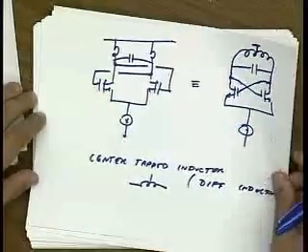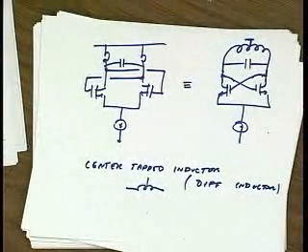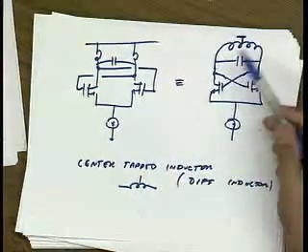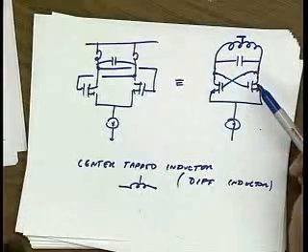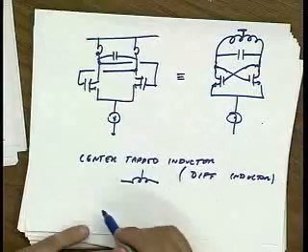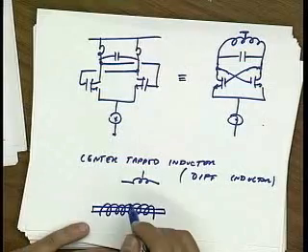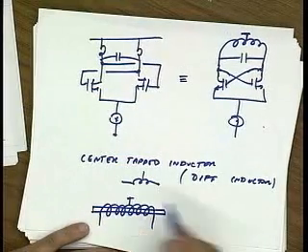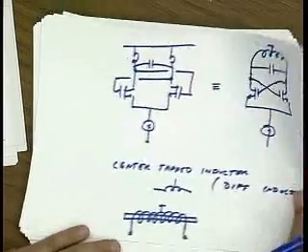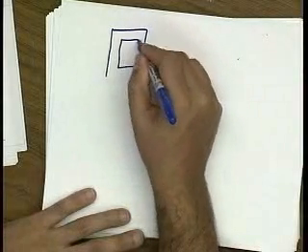So what do I mean by that? Okay, let me stop here and take some questions. Okay, what I mean is that I want to preserve symmetry in this circuit because symmetry helps me reject any kind of common mode signal. So if this inductor is off chip, let's say it's some kind of coil wound like this, and I tap the center, that's right, that's great. There's no problem there, right? The circuit looks very symmetric. But if I build this inductor on chip, it's probably going to be a spiral, so it might look something like this.